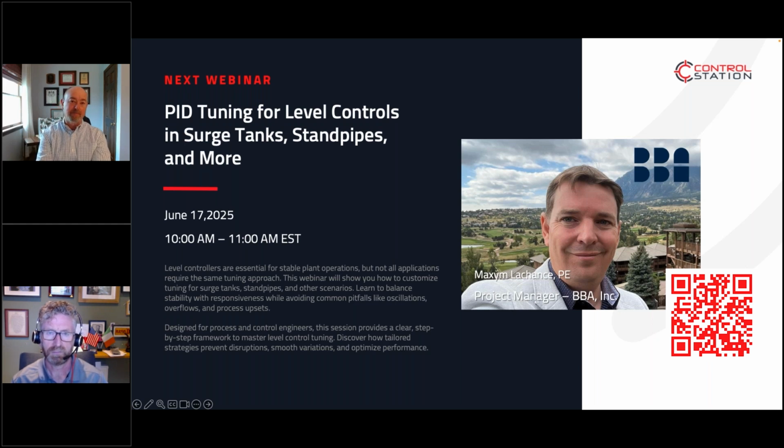There are some 100 to 200 decisions that go into selecting every single control valve, and you should put some emphasis in that process on not only whether I have the right size piece of equipment, but also how it will perform dynamically. Is it going to be capable of performing without stiction? Is it going to be capable of smooth operation throughout its range of control?